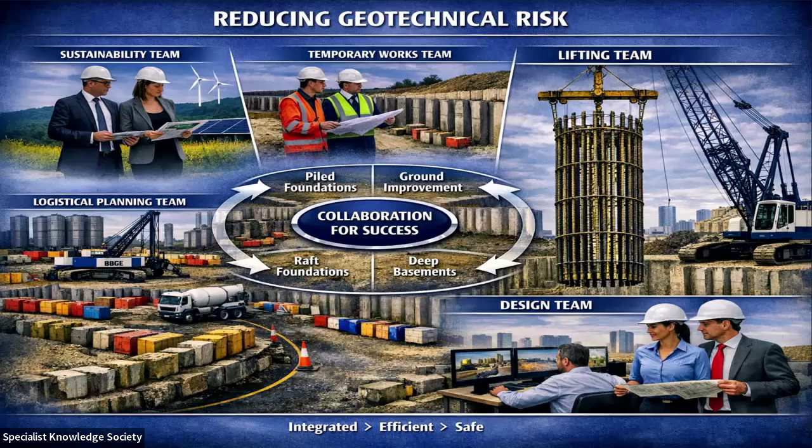I think that a driven solution, a displacement solution, is better where you've got a contaminated site, if you can get your displacement pile through that contaminated ground. Theoretically, it does create a path as you've driven it down to the non-contaminated ground below. But that is better than, if you've got a replacement pile, mixing material together.